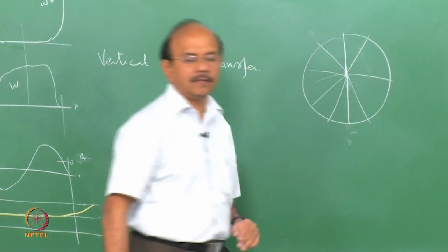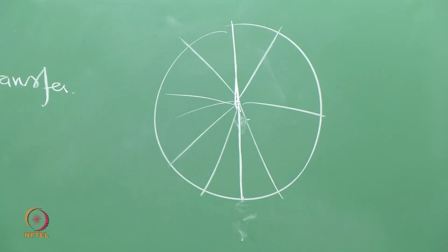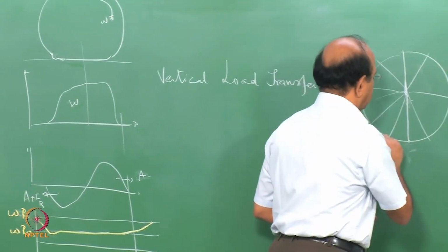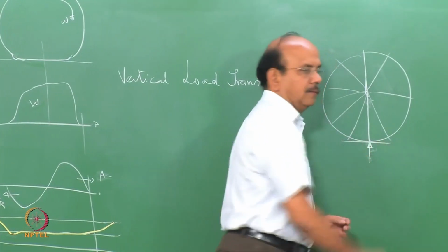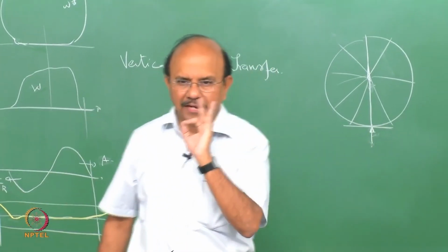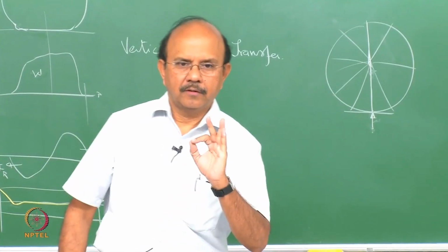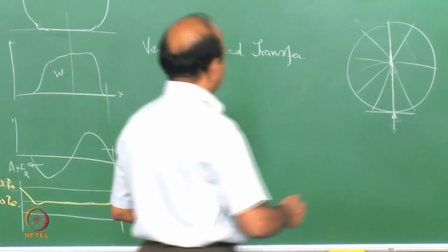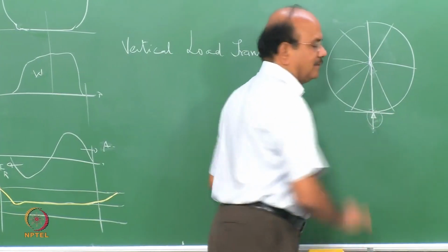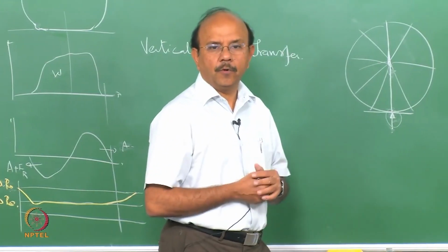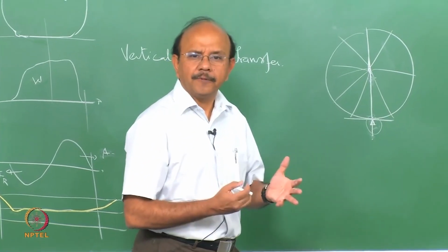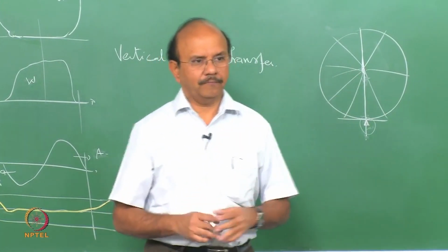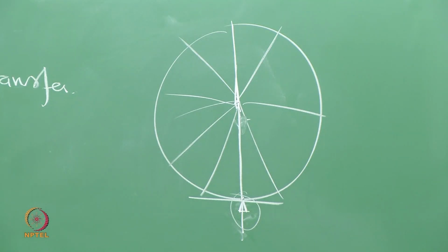Let's just consider a very simple situation. Forget about all other spokes. Now, this spoke is under tension. We'll consider just one for clarity. That spoke is on the ground, so there is a compression onto the spoke. So what really happens is that the tension here is reduced. Let's depict that with an arrow.